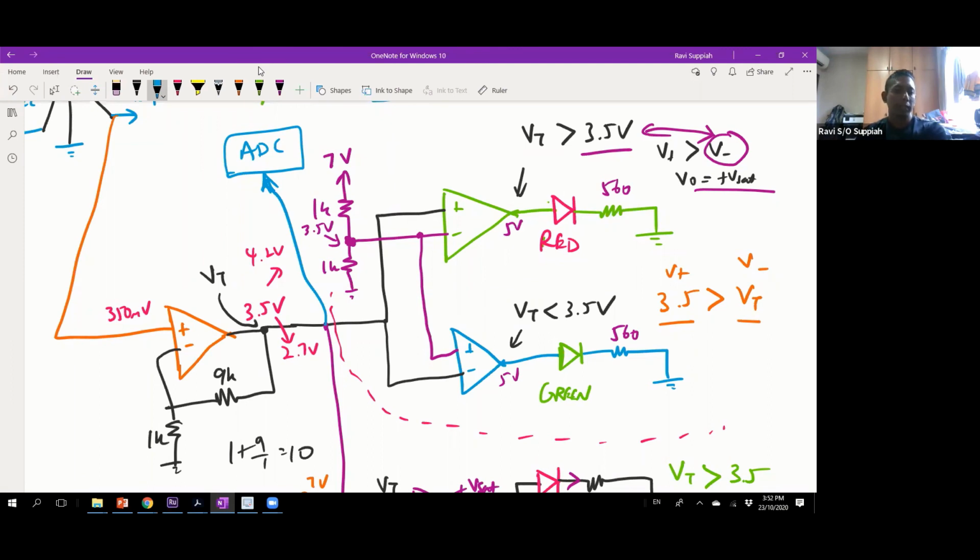Okay, so as much as possible, we just prepare the signal to give us a good signal to noise ratio. Okay, and then subsequently we do all the processing over at the software side. We do A to D conversion, take the digitized samples, and then we do all the processing later on in the controller. So in the controller, it's a lot easier for me to do all of this. Correct. In fact, this is the same idea you're going to use for your IR sensors, correct? Because IR sensors are giving you an analog voltage.